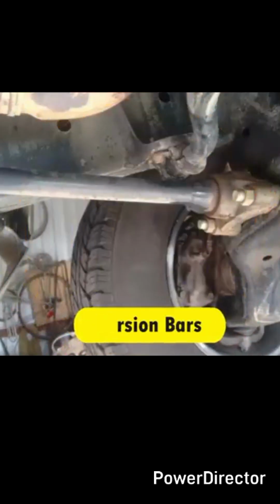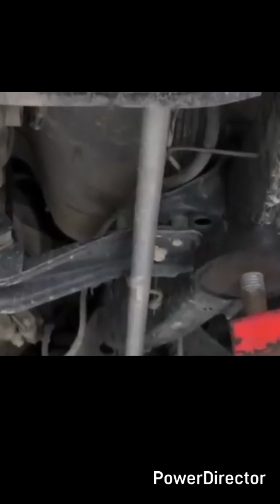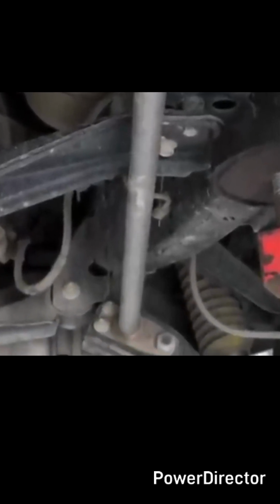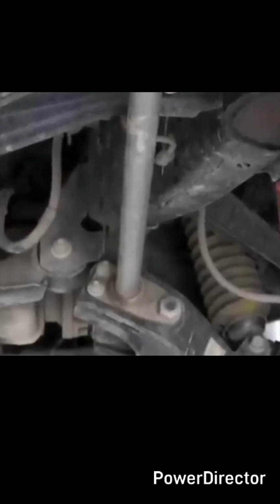A torsion bar is a metal tube with rods inside. They work on the principle of twisting. It means that before installation, torsion bars are torqued around the axle and then produce the force of untwisting. This function is controlled with special levers and shock absorbers, using the bars as an elasticity element.